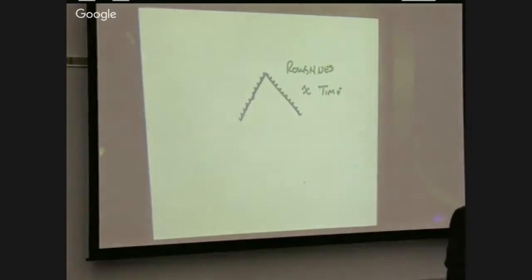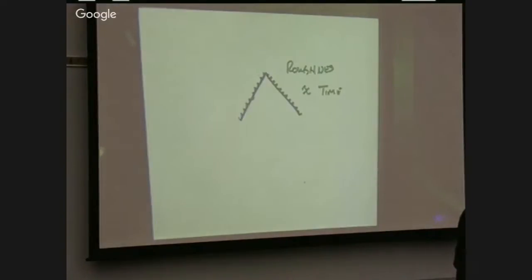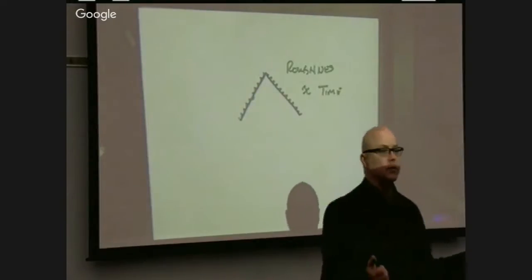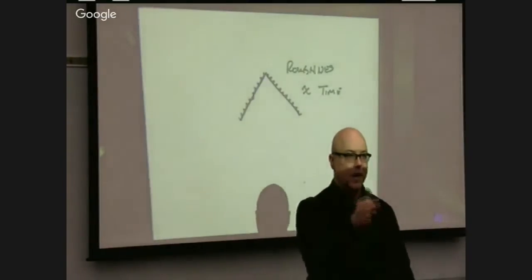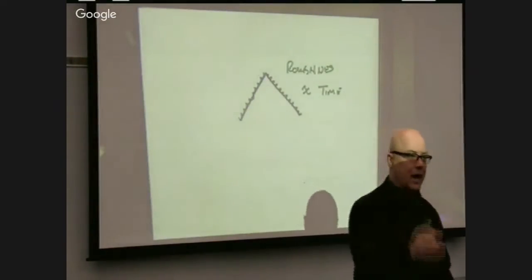How many parts are you doing? If you're going to make three parts ever, then you're probably not going to invest in a machine that costs more. The 5-axis machine typically costs more than a 3-axis machine. So how many parts you're making total, and what the throughput is, what the takt time is that you need those parts to be coming out.